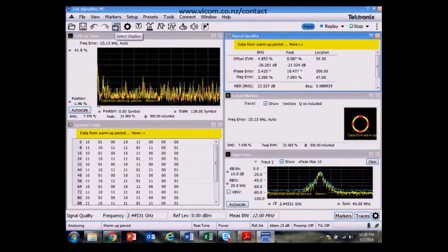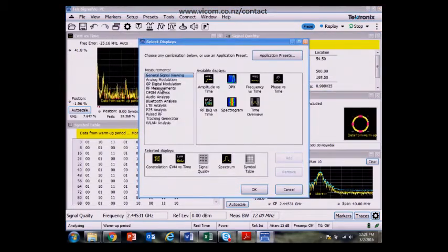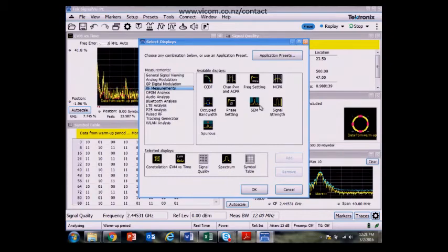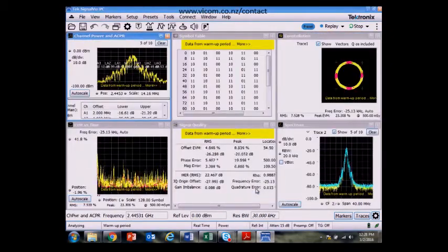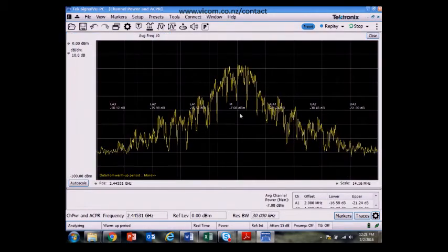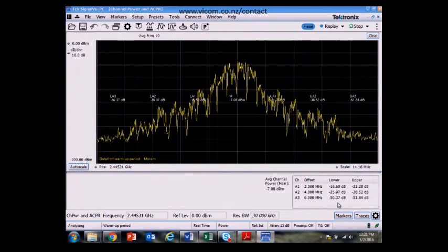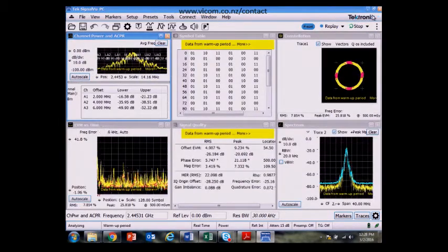Another type of test for parametric testing that's useful is if we go to RF measurements and bring up the channel power test. So I'm getting a very crowded display here. Make this larger. This is a channel power test that shows the main channel around -7 dBm, and a couple of the adjacent channel powers may be a little difficult to see on the screen, which is why we have a table reporting these results here as well. All of the measurements that you see here and in the demodulation are available programmatically to set up automatic test equipment code to get these results repetitively.